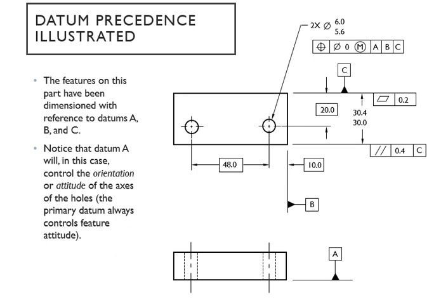and that. And here we are dealing with, look at this, the leader right here is talking about the 2 diameters right there, and you can see that tolerance right here. So these datums A, B, and C are going to deal with that dimension. So the measurement, and then we have parallelism and your flatness of the surface, and parallelism of these 2, the front and then the back of the surfaces.